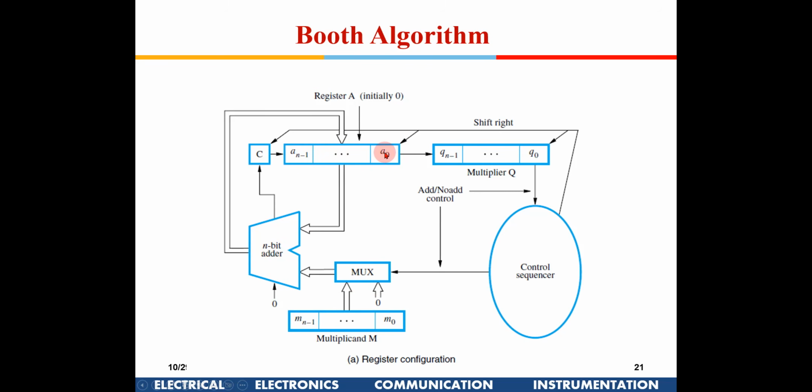This is one 64-bit register, 64-bit register, 64-bit register. Only thing is you require a clock which is fast. For modern day processors operating in gigahertz, this is fine enough. So the entire result will be available in a few nanoseconds.